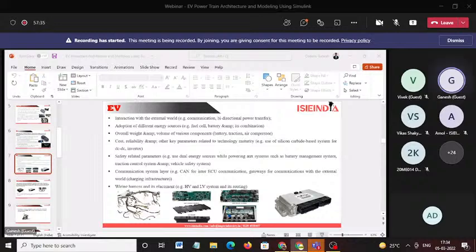Like if you see, the vehicle will suddenly behave unexpectedly. As I said, an electric vehicle can be very dangerous. Why? Because recently, some vehicles suddenly went into reverse mode, and sometimes they even blast. These are all due to some miscommunication between the VCU and the controller. There will be controller logics, and sometimes the logic will not be activated. So due to that, out of 100 vehicles, one vehicle might get this kind of issue.